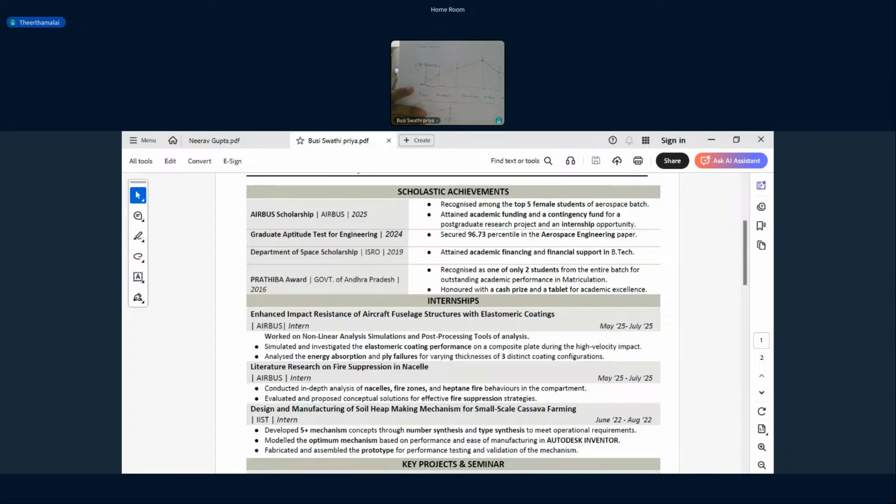In the combustion chamber, there will be sudden temperature addition, which you have not mentioned in this. At that point there will be heat addition and the temperature will increase. That sudden increase is not there. Otherwise, it looks okay. Even at the end, it will not go down to the free stream temperature. The exhaust temperature will be more than the free stream temperature.